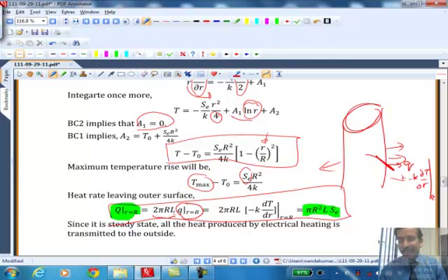Okay, so this is the surface area, and you multiply it by the flux, and of course, you need to evaluate the flux. That means you go to this expression and calculate dT/dr, and after you take the derivative, put lowercase r equal to capital R. That's how, like minus k times dT/dr, and then substitute, and you will find that you get exactly the same expression, which we kind of intuitively argued should be the volume times S_E, but you get exactly the same expression this way.